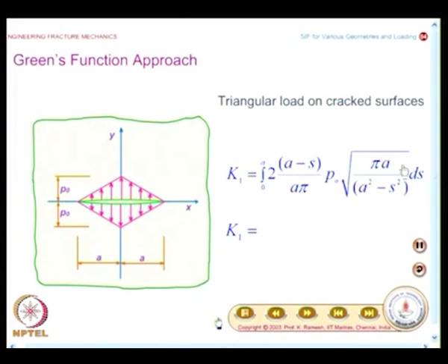See, if you had looked at when we wanted to find out energy release rate based on displacement of crack faces, we had a discussion that the crack is opened by a pressure which is equal to sigma, and we said some expression for the value of K, and we would see what kind of expression for K we would get. So, both the expressions are important, and what you will find is in each of these cases the integral will be different.